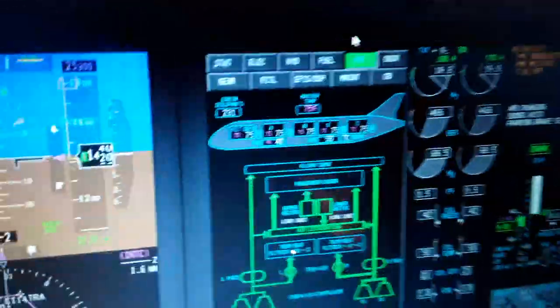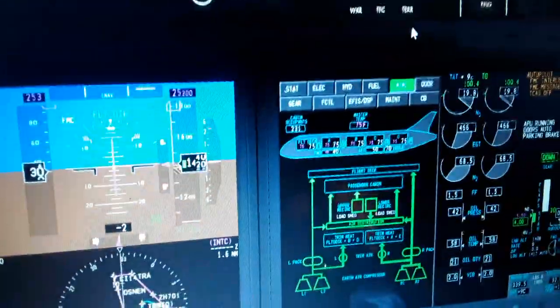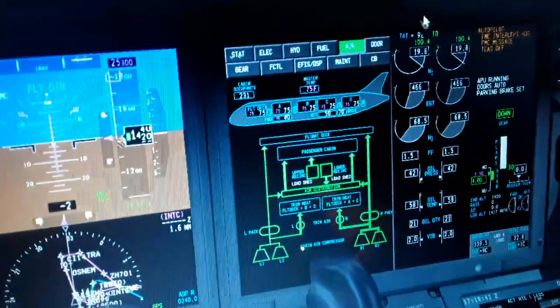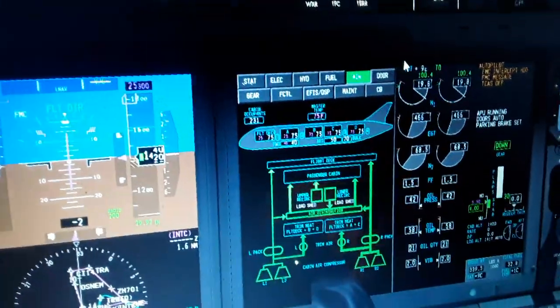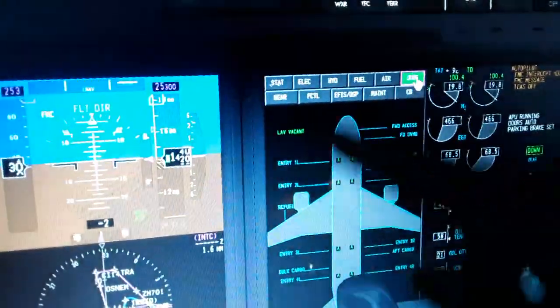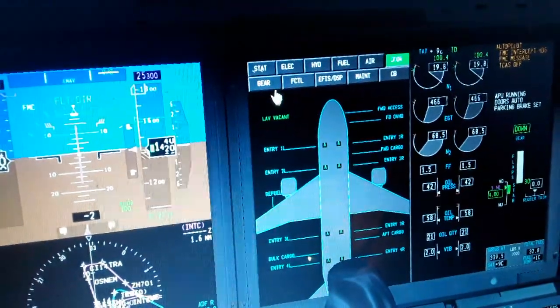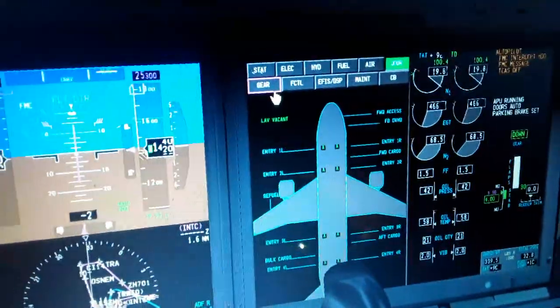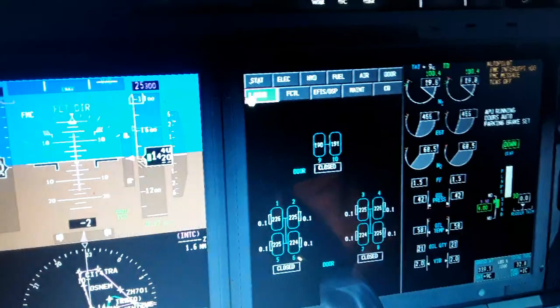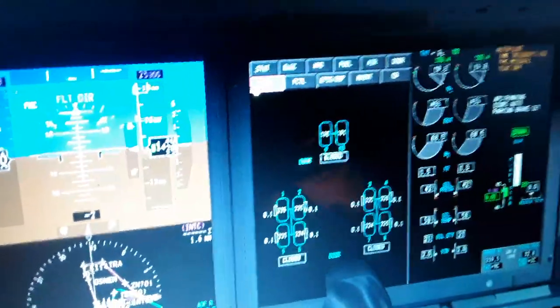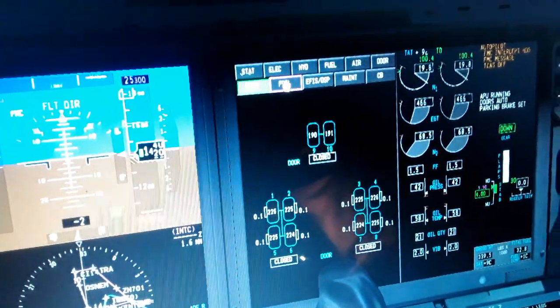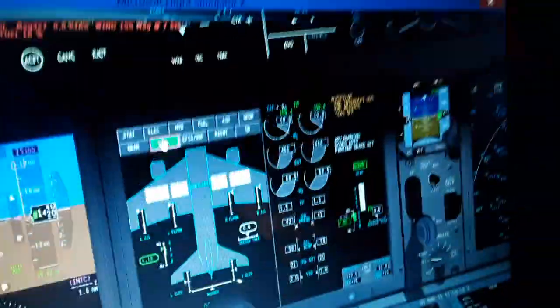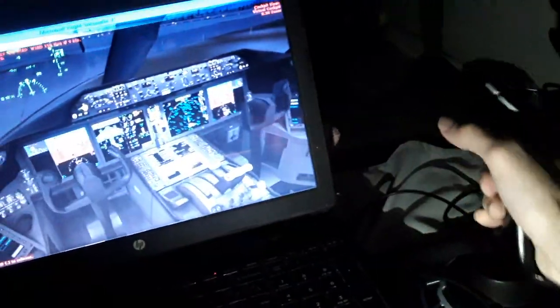The air system, the cockpit and the cabin, the pressure from the engines and the APU. The doors are closed, the cabin can be pressurized, the gear. You can see the temperature of the brakes here, and the pressure of the tires and the nose wheel, also flight controls, maybe last system to see. So you see the flight controls over here. Alright, everything is working normally.